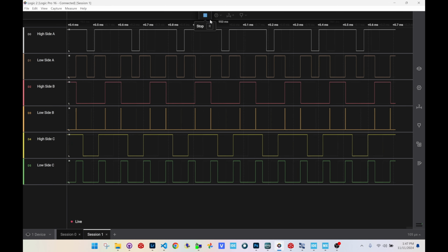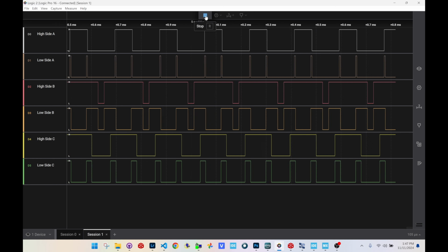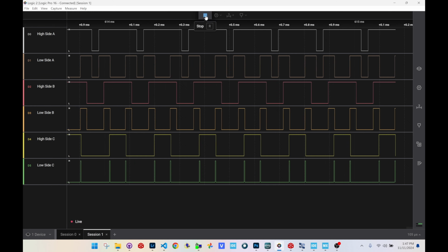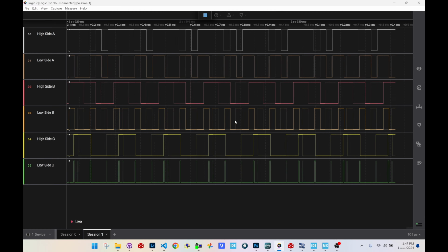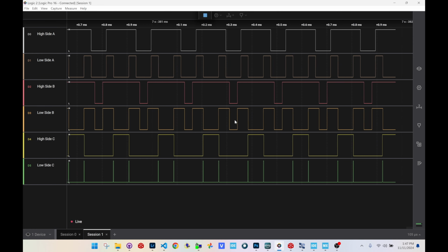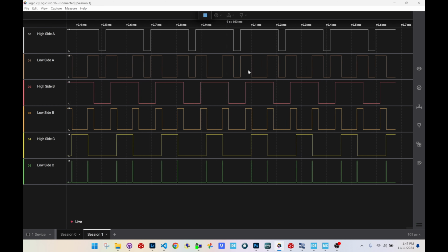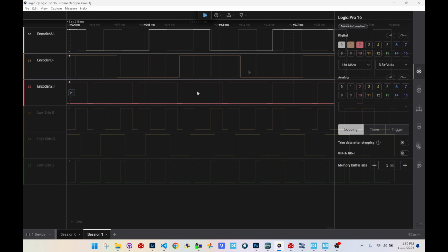If you look closely at the oscope capture, you can see how the phases of the PWM are out of phase by 120 degrees apiece. If you look at the high side and low side signals, you can see that there's dead time built into the low side. Timer 1 is used to drive the high side, and timer 8 is used to drive the low side. Timer 1 is used to start timer 8, so the timers are perfectly in sync. Timer 8 uses the AND mode in order to create the dead time. All we have to do is set the compare register 5, and that's used to AND all the signals.